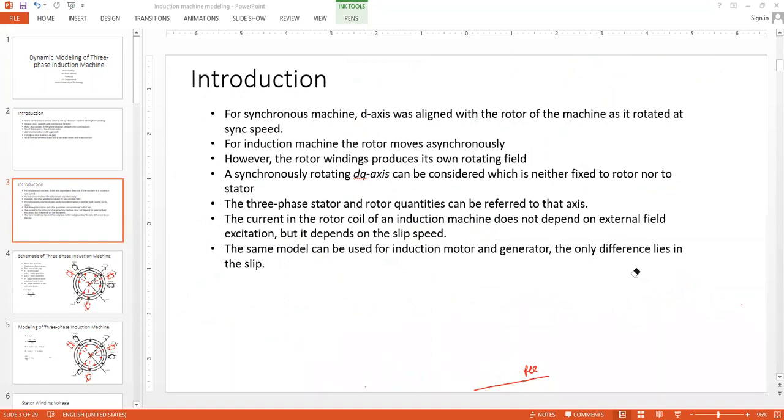A single-phase machine has a completely different scenario. You have to introduce the capacitance, or you have to somehow split the phases, otherwise you have pulsating torque. That is a different thing. I'm talking about a three-phase machine, remember, not a single-phase machine. Everything that I'm talking about in this lecture is solely related to the three-phase induction machine.